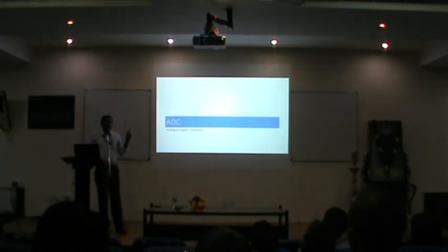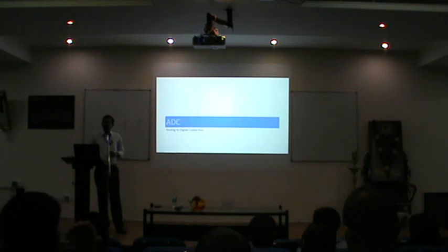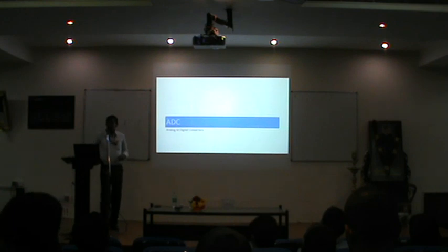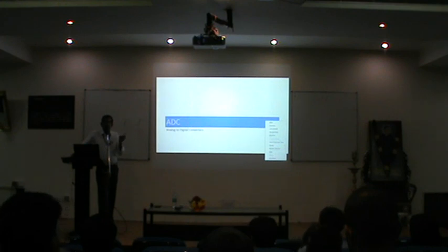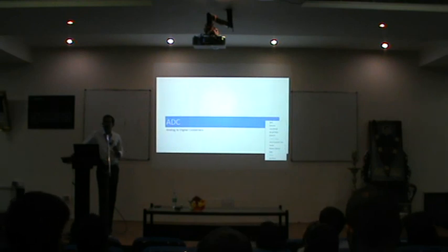Now these are related to control aspects. We covered only PWM because that was the important topic related to any kind of converter control. Other things we didn't touch. We will come to the sensing part. So you will have a requirement when it comes to motor control, a requirement to sense the load current, load voltage, next speed, direction of the motor. Physical quantity, electrical quantities, current, voltage. So obviously you need a device to sense these voltage and currents. Motor control, I am not taking other environmental parameters, only voltage and current.